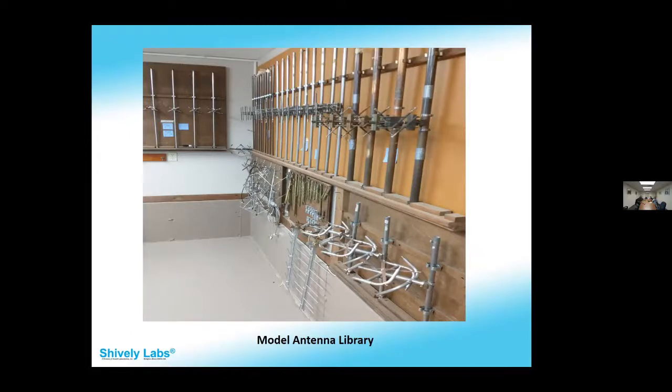Gating, electronically removing that ground bounce, is also possible. So what you end up with is usually a series of tools that you use to your advantage to reduce that. Yeah, in loudspeaker work, they do impulse response, and so they reject everything after the initial arriving signal, so the reflections are not included. Yeah, that's a great technique as well. I can't think of how we might implement that, but it gets tricky when the reflecting surface is close because everything arrives at about the same time. Right. Yeah.